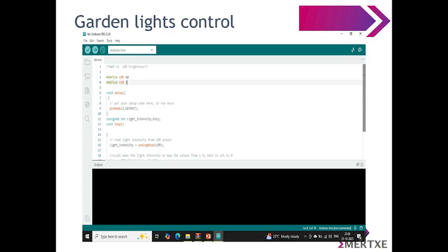And here we have given the duty, a term used when working with pulse width modulation, meaning how long the signal stays on compared to the total time of one cycle. Pulse width modulation is a method to control the amount of power given to a device by turning it on and off very quickly, and we use it mostly in controlling LED brightness, adjusting motor speed, controlling a servo motor and regulating the power in a circuit.